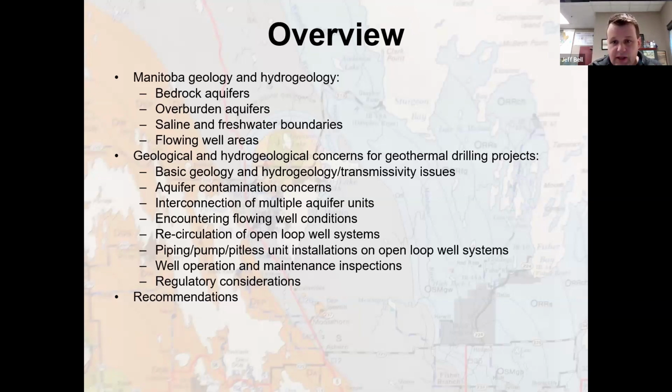grade. I'll get back into sort of the reason why we're all here, I guess, is to discuss some of these things in relation to when people try to do geothermal. Some of these basic geology and hydrogeology things that we take for granted often can cause problems for us. Transmissivity issues in the bedrock, which I'll get into further.